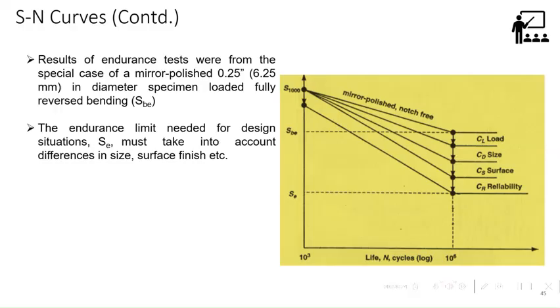Yeah, but sir, as we know, many of the SN curves are generated for fully reversed loading, right? But in practical scenarios, most components go for non-zero mean stress. So is any mean stress correction needed? Obviously, it is required. That will come. The effect of mean stress is one of the subtopics.